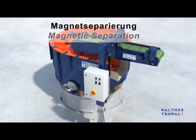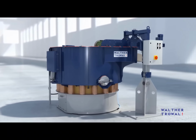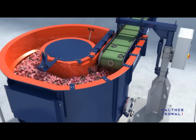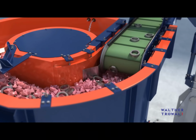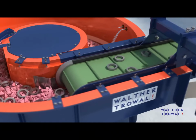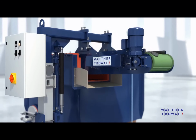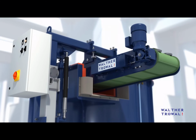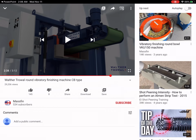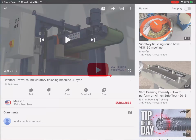Workpieces made from carbon steel can be separated from the media with a magnetic belt separator. In this case, no separation screens are required. The finished workpieces and media are guided onto a polyurethane plate from where the media falls back into the processing bowl. The workpieces are picked up by the magnetic separator and pass over a demagnetizing zone integrated into the belt before they are transferred to the next manufacturing step. Next one is mass finishing.